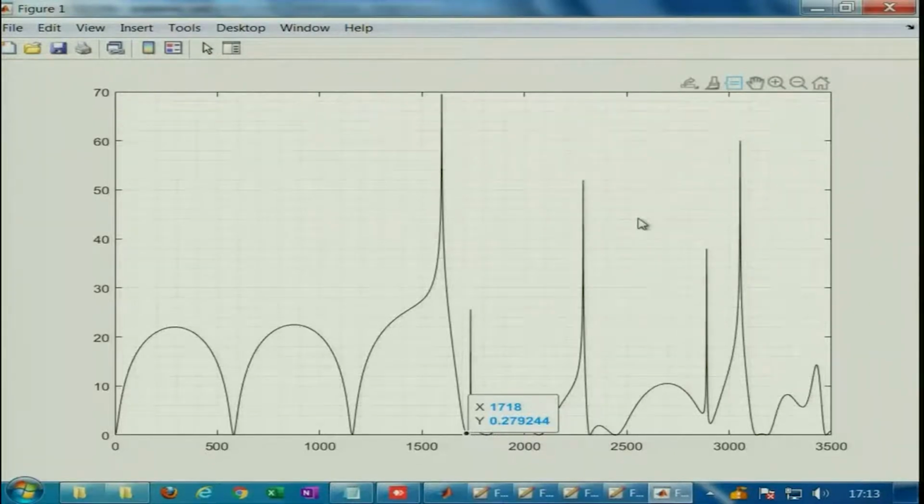Then after that, beyond this first radial mode, everything is pretty much useless. Although the values are accurate, I mean to say the muffler performance goes down after the onset of the first radial mode for a concentric simple expansion chamber. Okay. But for extended inlet and outlet, we will see how these things can be further controlled. What is going to happen is that beyond the 0-1 radial mode, you still do not get a very good performance, but at least it will not be as useless as this.